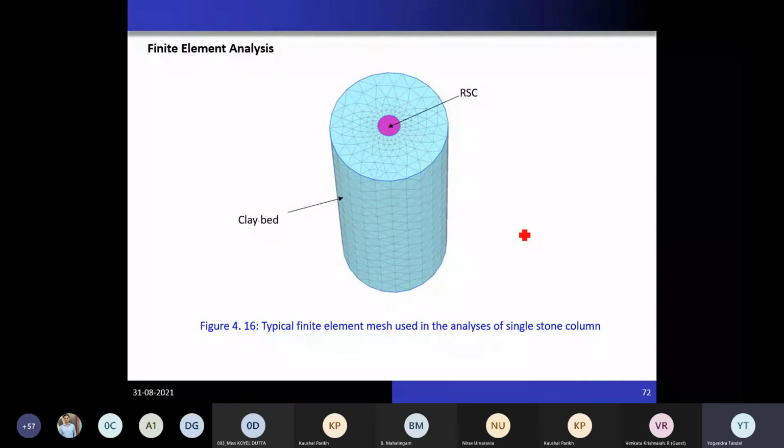Okay, so you need to take care while doing numerical modeling. Very often it is observed that you have a certain experimental value, you do the numerical analysis once, and you don't get a match between the experimental value and the numerical value. The thing is that you have to take care of the meshing, in the sense that you have to go for a convergence analysis. You have to go for a number of meshings, from a very coarse to a very fine mesh configuration, and you have to compare your numerical results with the experiment.